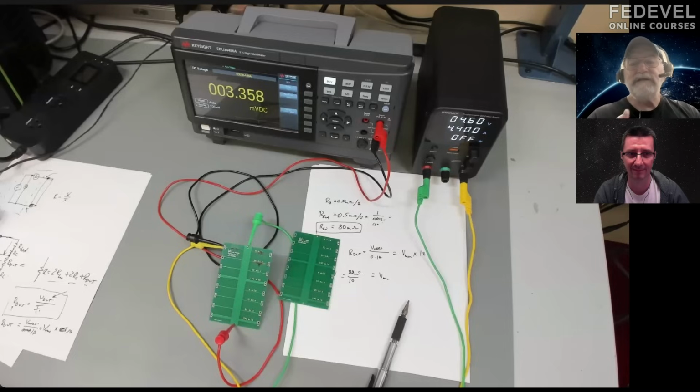And the technique usually is you distribute high voltage, lower current, and then you have point of load VRMs that go from the higher voltage down to the 1 volt for the rail, and that's where you get the current. They're placed very close to the load. Yeah, precisely for this issue of that series resistance.